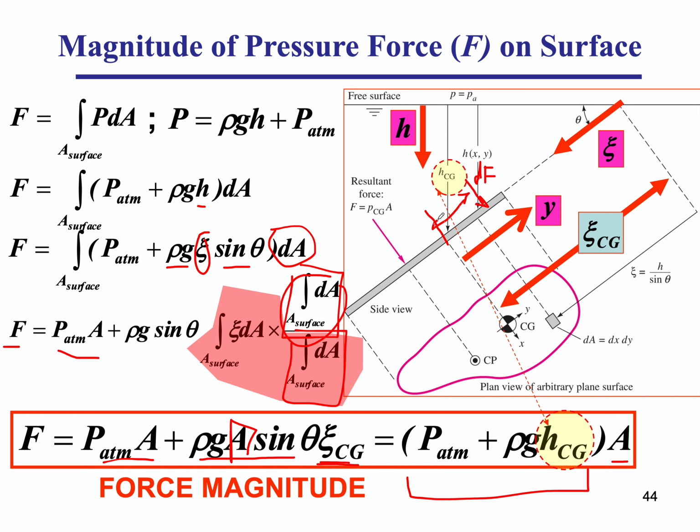So I'll pick the center of gravity, and I will get dF times the distance from this object to the center of gravity, because I've located my center of gravity at 0, which is equal to y. So the moment dm is y dF. The moment of this hydrostatic pressure force around the center of gravity is just y times dF.